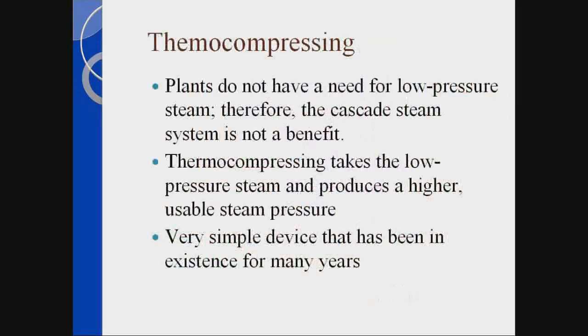The other thing, the question always comes up in comments from plants: we don't have use for low pressure steam. What can we do? The thing with the low pressure systems is that we can thermal compress the steam. Therefore, we can take the low pressure steam and thermal compress it to a higher usable steam pressure.